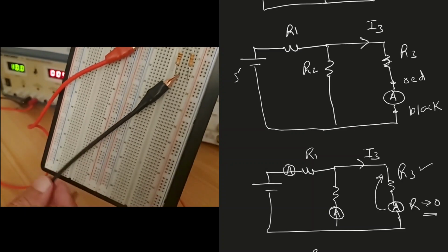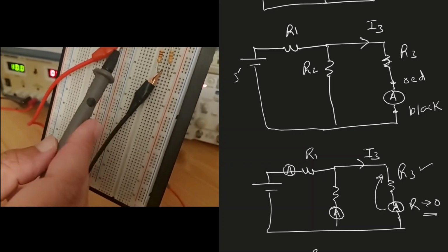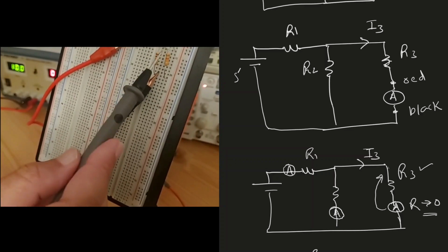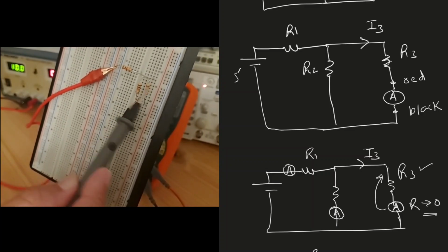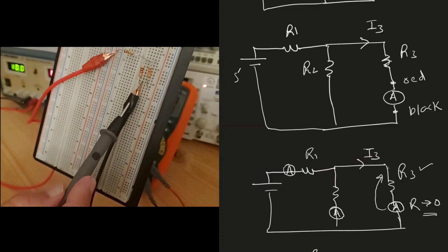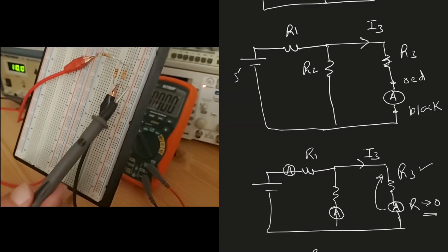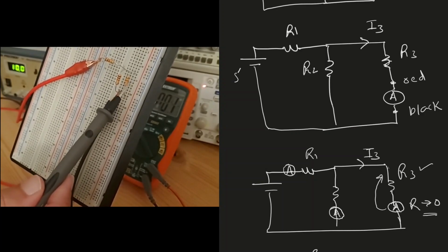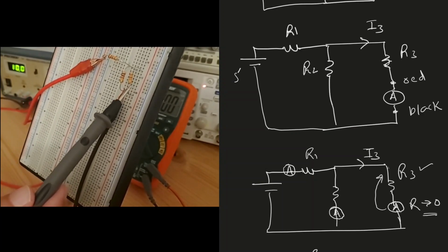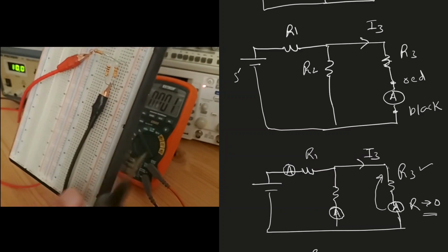Right, so now I have constructed the circuit, and you can see that the current will flow through these resistors, and then the current will divide between these two resistors, and then it will go to the negative probe and go back to the power supply. Okay, now let's say I want to measure the current in this resistor, 3.3 kilo ohms, right? So I want to measure in this resistor.